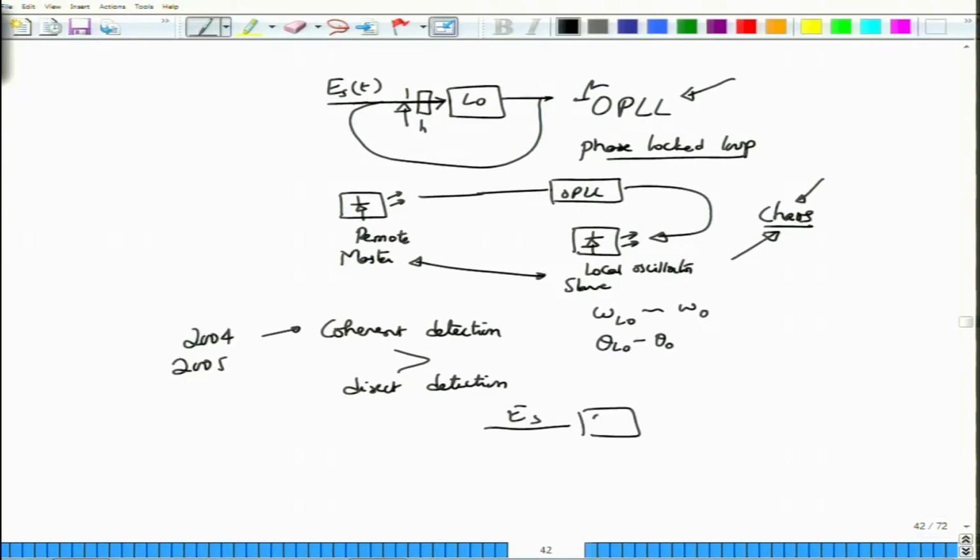You have your coherent receiver, you generate the in-phase and the quadrature components. I am showing a single coherent receiver, but this is a phase diversity receiver, of course. So this coherent receiver of course also takes in ELO. I am going to stop tuning ELO with ES, but what are the problems that I could have? Well, omega LO may not be exactly equal to omega 0. This problem is known as the frequency offset problem.